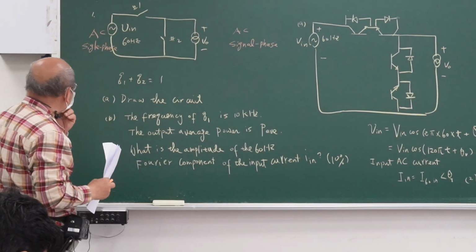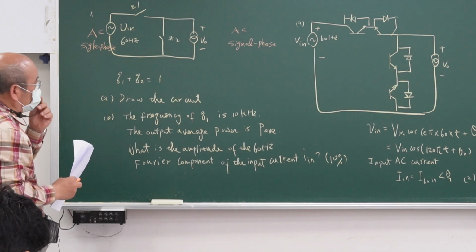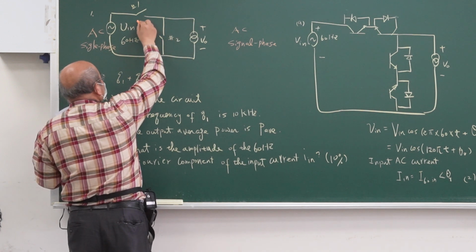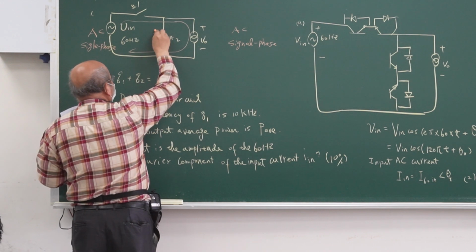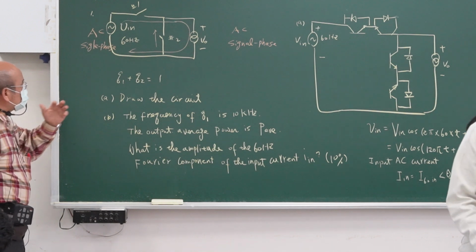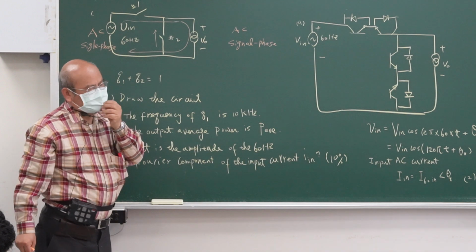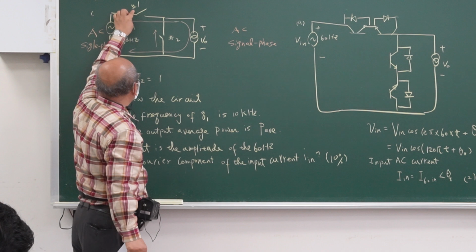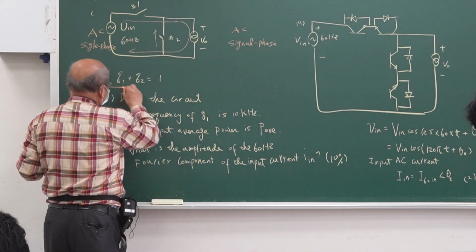So we have two switches, switch 1 and switch 2. This is a current sink, so you can see the current can go this way or the current can go this way. According to our rules, the output current cannot be interrupted. So Q1 plus Q2 should be equal to 1. This is the general rule.